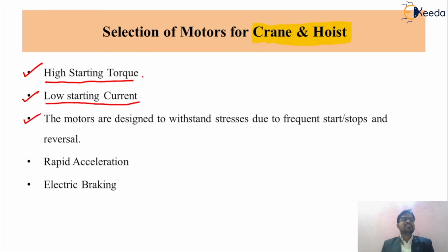The third selection criterion: the motors are designed to withstand stresses due to frequent starts, stops and reversals. As we know, in crane and hoist applications in different industries, we require frequent start and stop, and sometimes a speed reversal, so the motor should withstand the stress. That is a very important criterion while selecting a motor for a particular application.